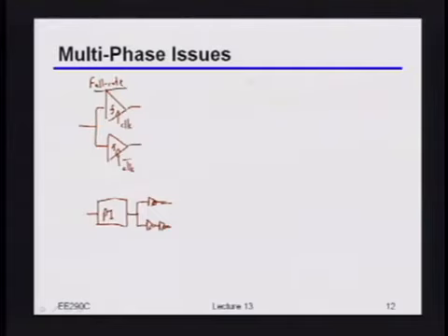But let's say that we actually wanted to use multiple clock phases. So we wanted to do time interleaving because we want to run really, really fast, much faster than we could get an oscillator, or at least a ring oscillator, to run. Let's take the simple example where you do what's called double data rate, often referred to as DDR.